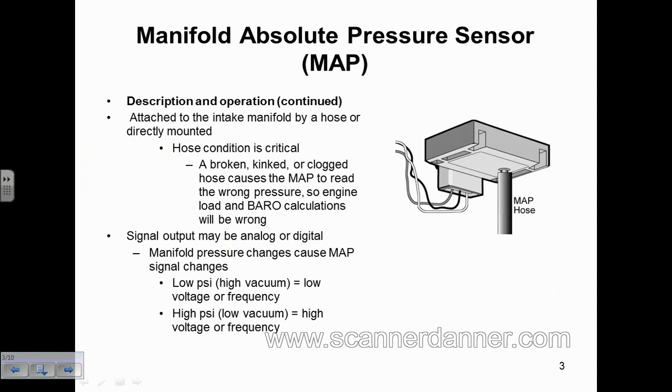Ford didn't do that, but GM did. Most of the GMs that have mass airflow sensors also have MAP sensors. It does change things a little bit. Primary function is EGR flow monitoring. In fact, some of the cars, I've seen this, I think Nissan is one, that have mass airflow engines actually call it a different name. It's actually a MAP sensor, but they call it something else because its purpose is EGR flow monitoring. I forget what they call it. Some type of pressure sensor. It is a MAP sensor, but it has a different name. They don't call it a MAP.